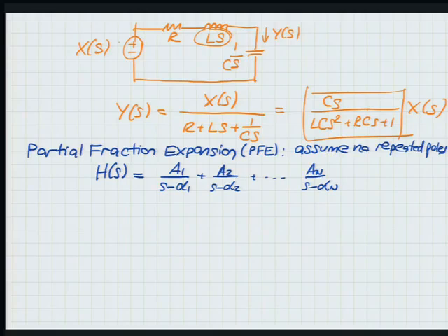So then what do we make of this? Well, looking at this, you can actually tell me the inverse Laplace transform very easily, right? Which is, of course, this being the transfer function, inverse Laplace transform is the impulse response. So what's the impulse response? I'm going to assume causality because circuits and other physical systems run forwards in time.